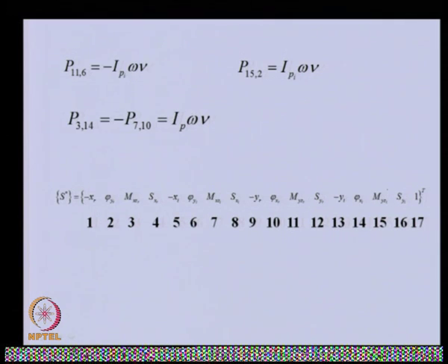That means each displacement will be represented as imaginary and real. Similarly, y and other displacements, and also shear force and bending moment, every one will have 2 parts, because now we are considering 2 planes. So, their phase may be different. To take care of that, we are writing them in the form of a vector or a complex quantity. So, you can see this is the stacking of the state vector.